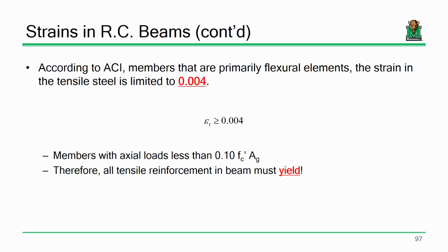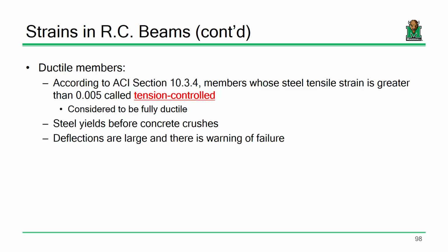We're talking about beams right now. What limit would this not be appropriate for? Columns, because columns aren't experiencing any tension. They're just pure compression. So this wouldn't even make sense to apply for a column because there's no tension at all. So it's something you've got to be aware of. Sometimes a lot of these limits are generalized, but then they'll have language like this. What they're basically saying is we're not talking about columns here. So this is a limit purely for flexural elements that are experiencing compression and tension. Okay. So far, so good?